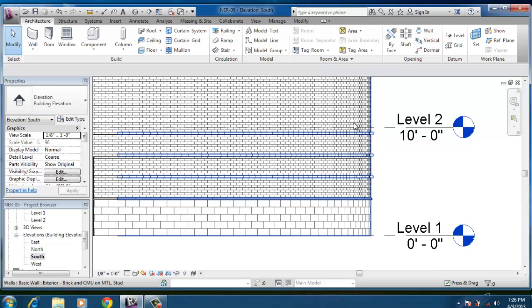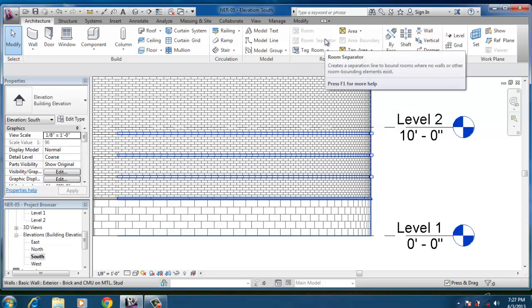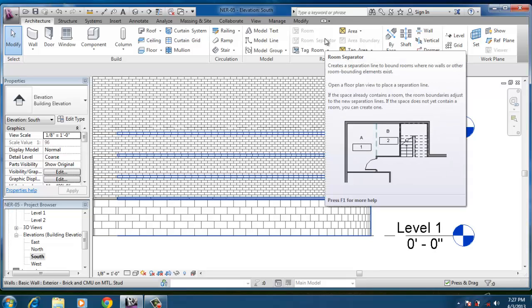Now moving on to adding levels. Adding an entirely new level in Revit Architecture is actually quite simple, but there are procedures that need to be adhered to in order to ensure you are adding the levels correctly. When you are using the level feature in Revit, two procedural aspects stand out. One is to look at your options bar after you start the command. Second is to click the modify button when you have finished.